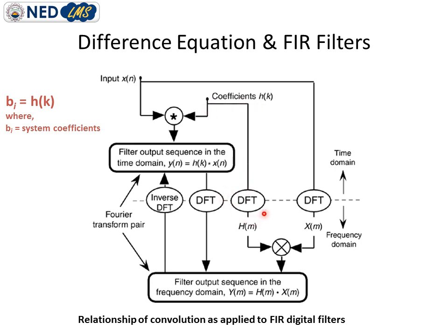We are taking the DFT of the impulse response. So by taking DFT, we are converting the impulse response into the frequency domain. So here we get the frequency domain version of these two inputs, the actual input signal and the impulse response, but both are in frequency domain now.